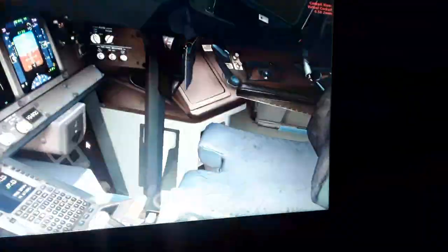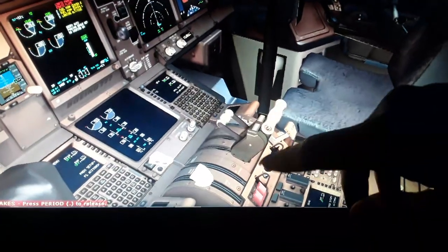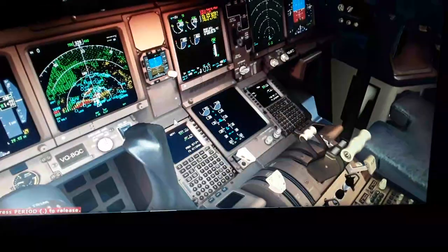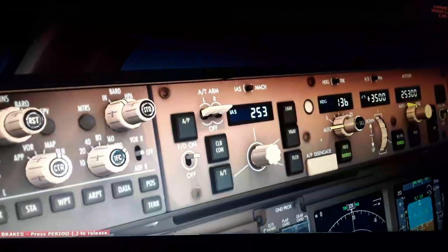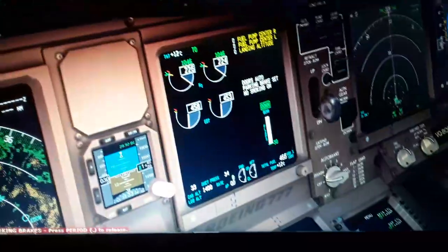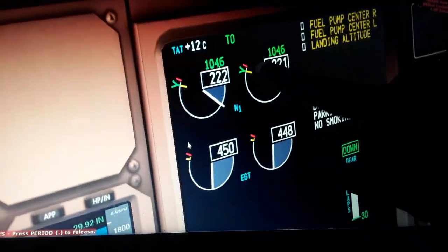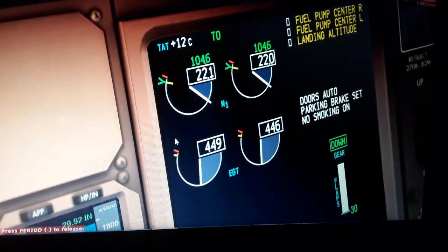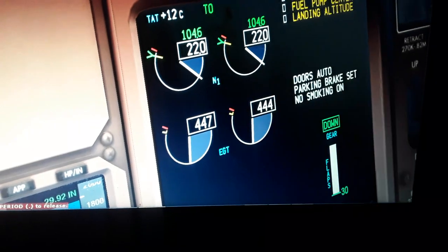You can see if we move the thrust levers, it gives a signal to the FADECs. The FADECs are the full authority digital electronic control computers. So you see here the signal gives the display, the upper and the lower EICAS. You use also the autopilot for that, for the airspeed command. So you have 104.6% takeoff limit with green, maximum continuous the yellow, and the red.